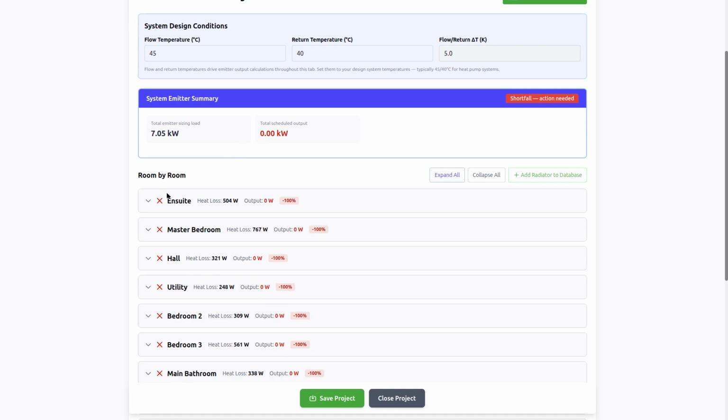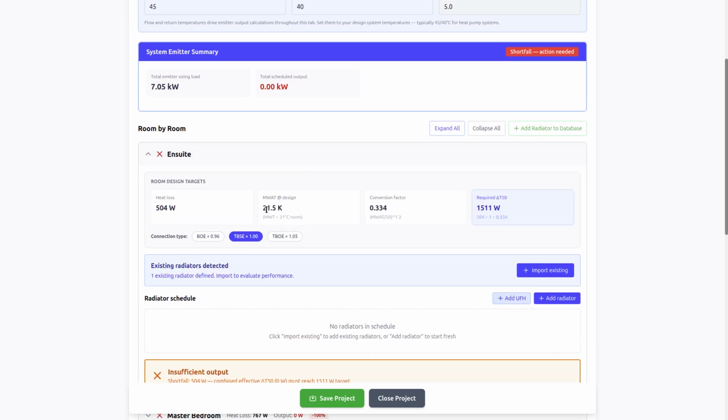What happens then is that the difference between the water temperature and the surrounding air is lower. And if you think about the way heat moves, the greater the difference between the hot element and the cold element, the greater the transfer of heat. The closer they are together, the less there is a transfer of heat.